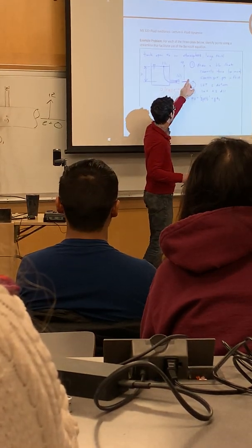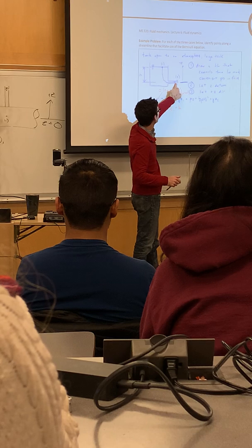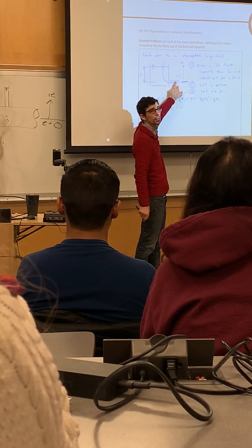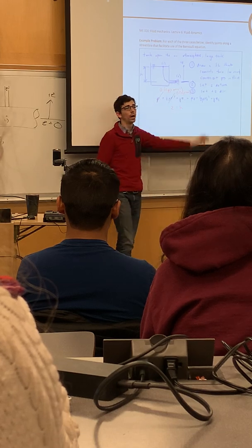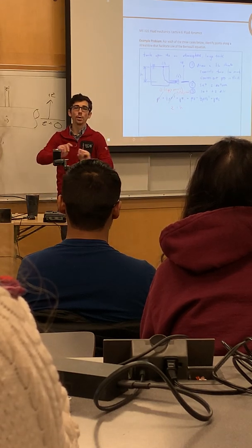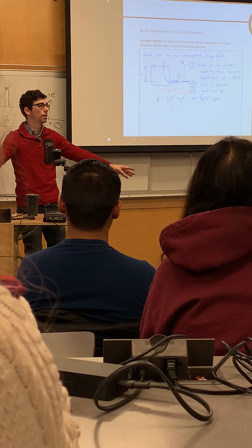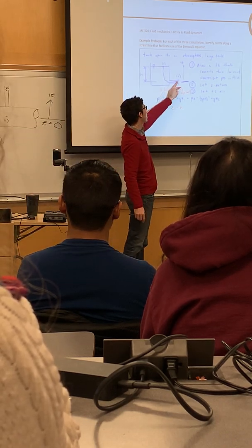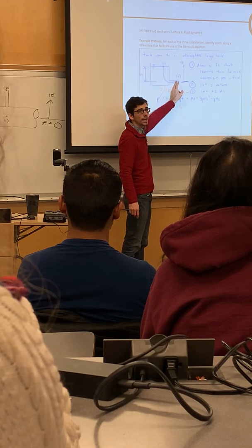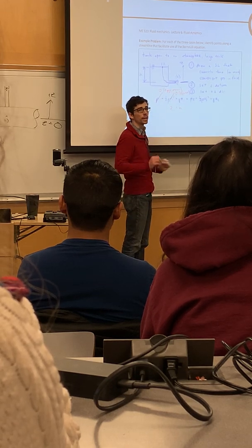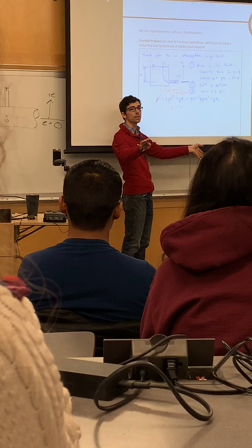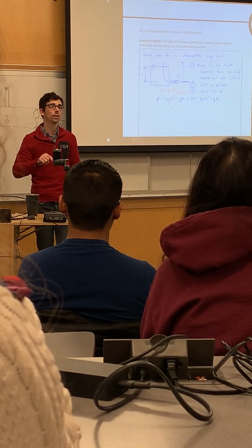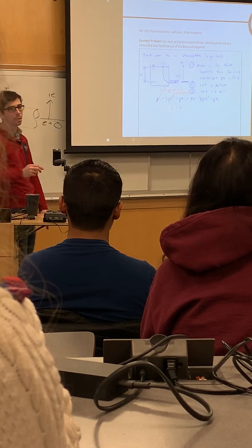Right? We have fluid moving out of here. We've drawn this point at the exit of the nozzle. So that's a typical sort of convenient point that you'll take. If you have a nozzle and you're told that it's flowing open to the atmosphere, I'd suggest you drop a point right at that exit of the nozzle. Because at that point, your fluid has entered an unconfined space. It's an unconfined flow. And you can take its static pressure to be exactly 0.